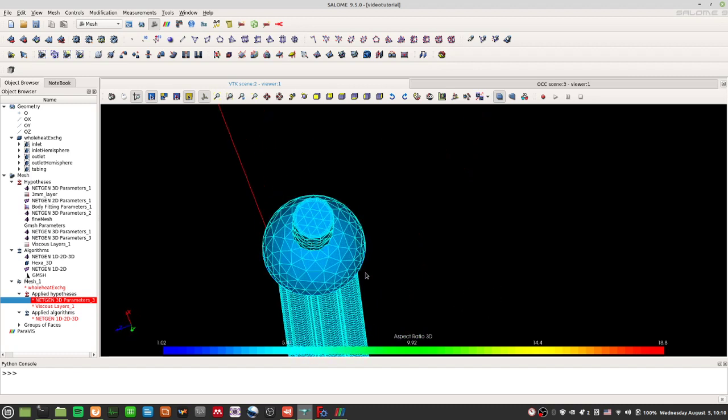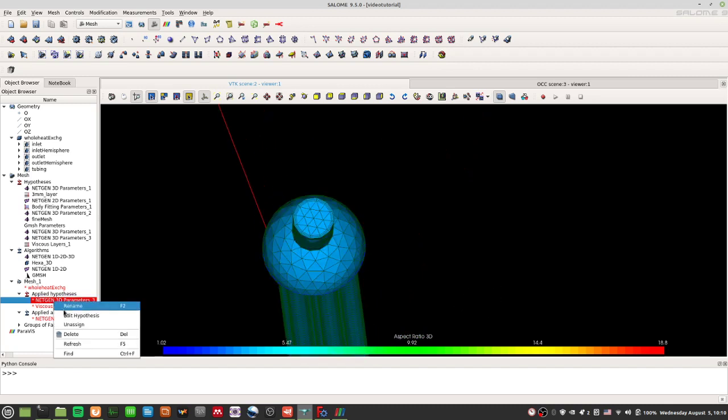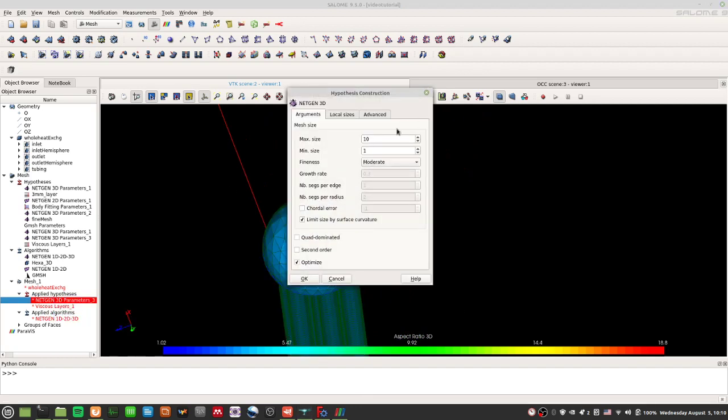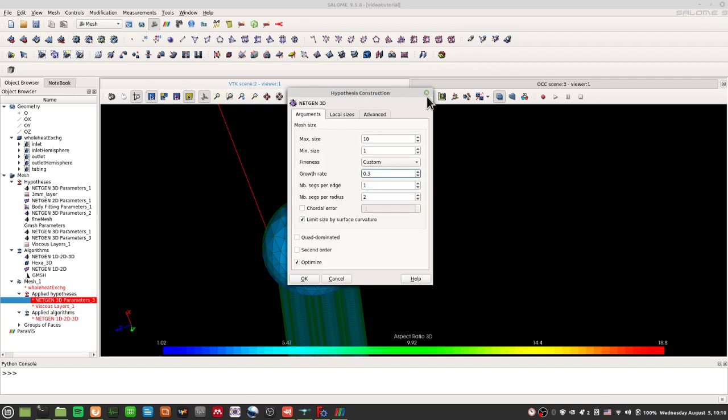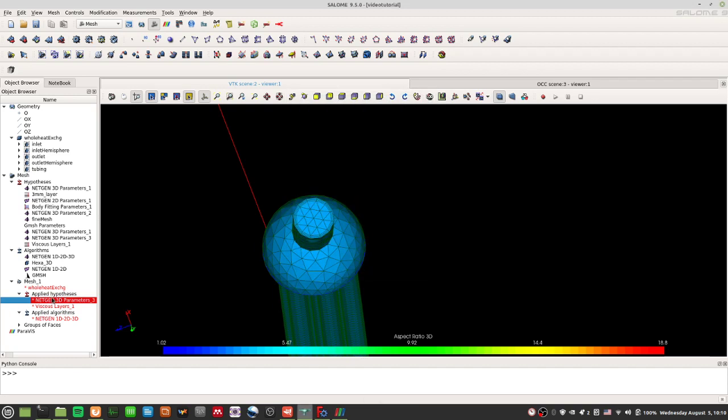Besides adding boundary layers, you can adjust fineness as I just showed you. You can adjust the fineness, which is actually the growth rate from the wall. It means that there's a less difference between the sizes; you can change the relative rate of difference between the maximum and minimum sizes. Of course, you can do lots of other stuff as well.